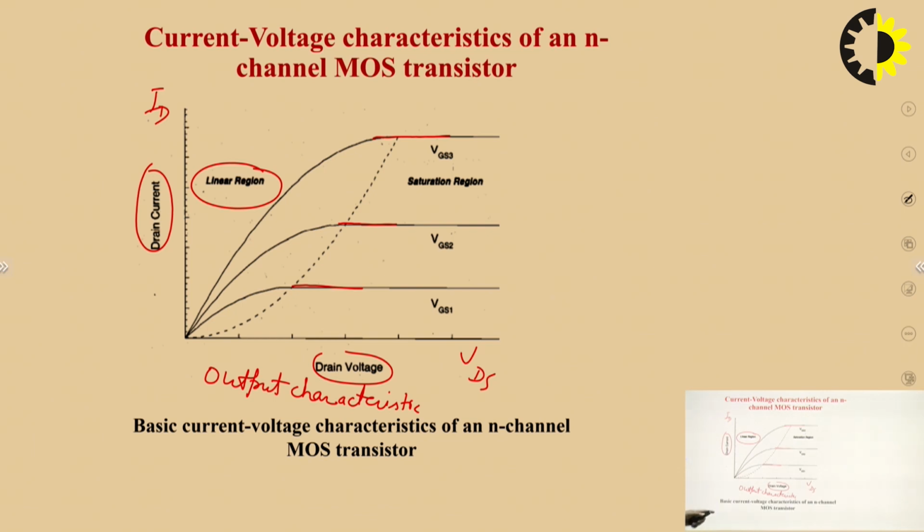And the current is becoming constant, it is being saturated, because when the drain voltage is greater than saturation voltage, the channel width ceases to exist at the drain end, and the depletion region keeps growing towards the source. So the current in that case flows because of the high electric field from the point of pinch off.